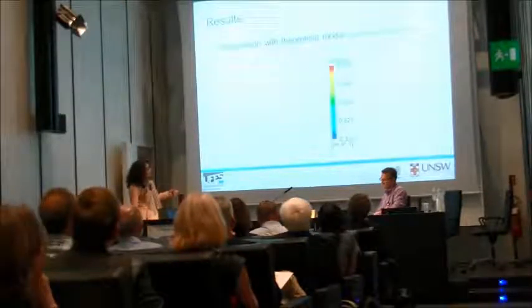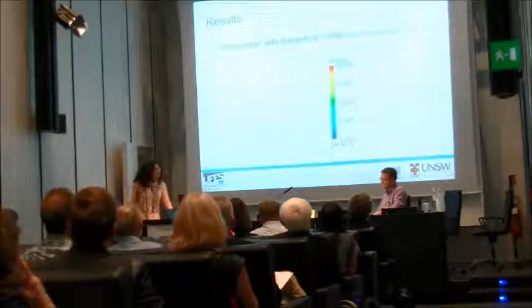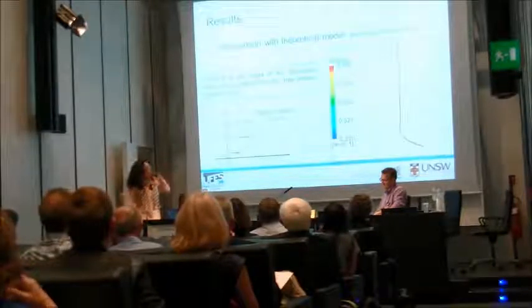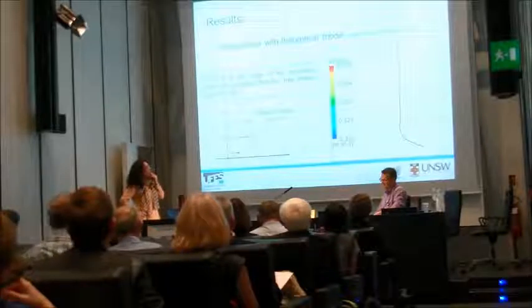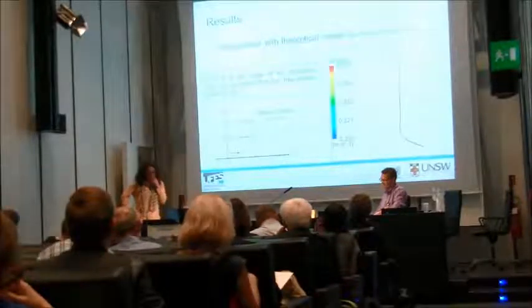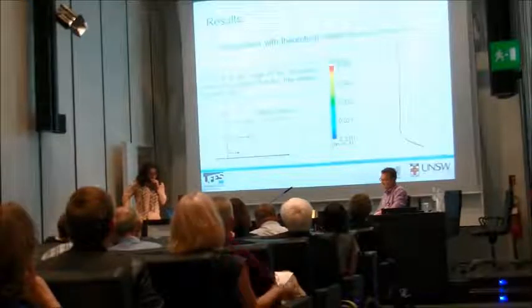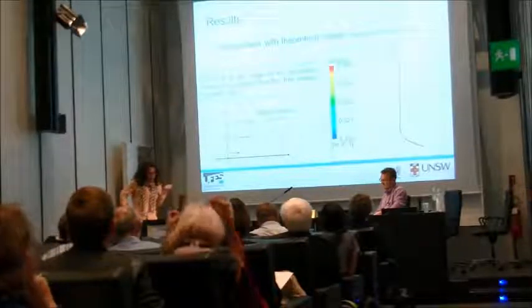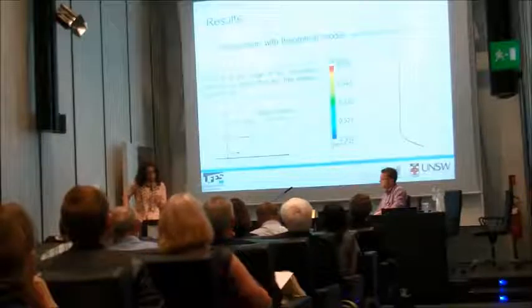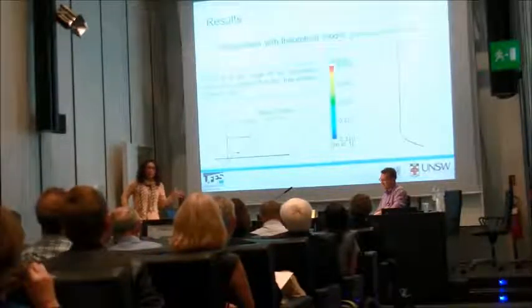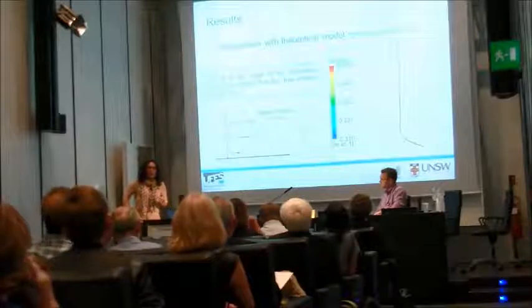And then we try to see, oh, sorry, it's a bit light there. We try to see the velocity profile we got, and then we realized that it's not a well-developed flow. So that brings us to the first thing I said about the Reynolds number. So we have to try to get away from the velocity we use.